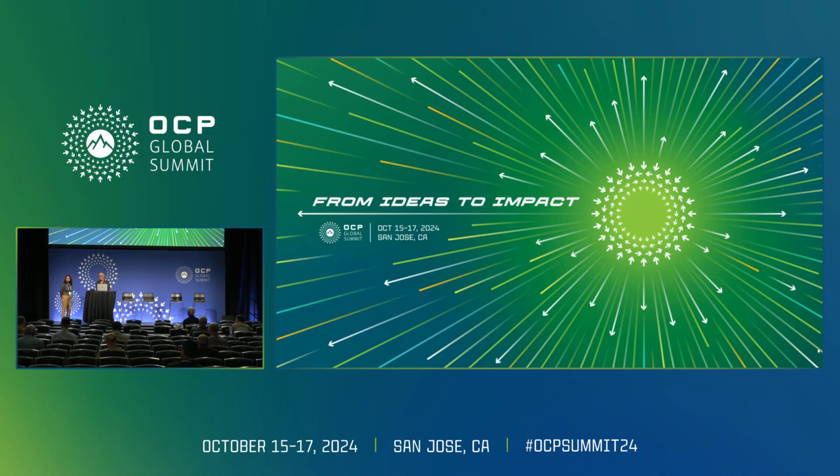I have a question. It's my pet peeve about known good die: you need probe to be able to produce it, but today we can't probe the micro bumps. So there's this concept of sacrificial pads. How do you see probe technology at some point trying to keep up with micro bumps getting smaller in diameter and the pitch reducing, but no ability to test them?